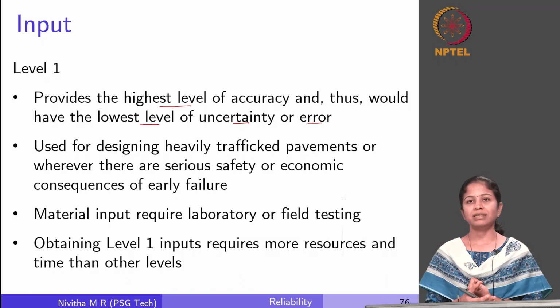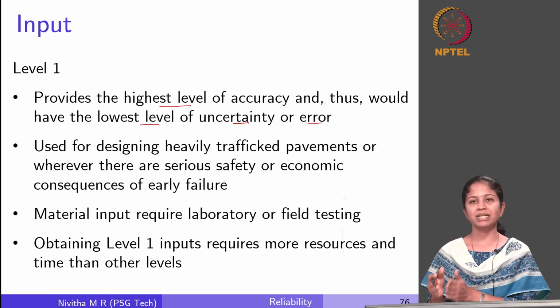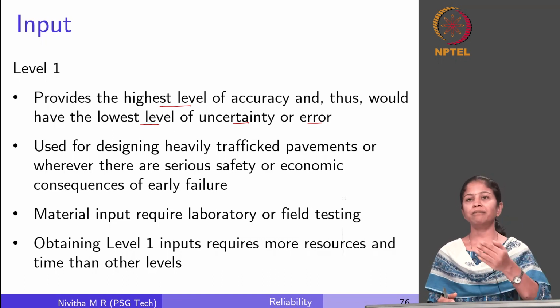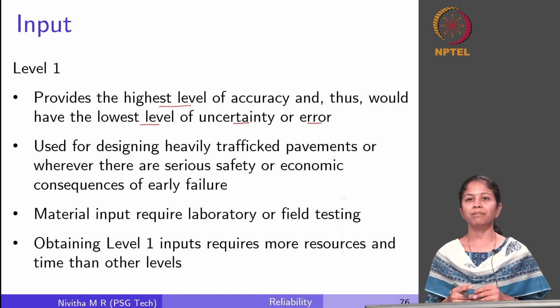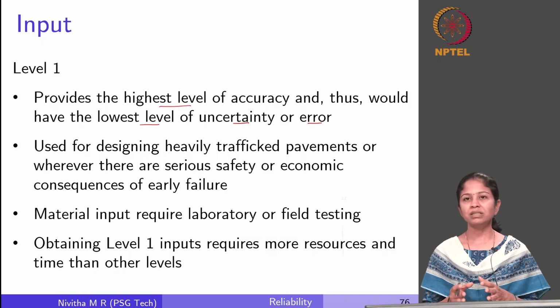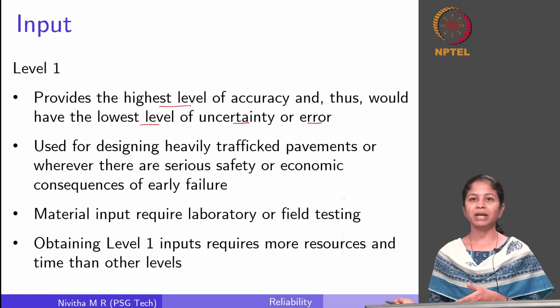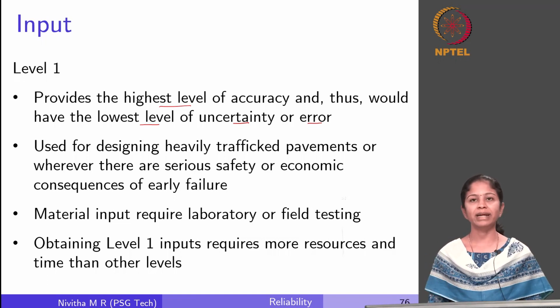Again, you know that this test has to be conducted at different frequencies and different test temperatures. So I conduct the test at all those frequencies and test temperatures. I input this information into the design procedure, and the design procedure will arrive at a master curve for this, so that for any combination of temperature and frequency the modulus value can be arrived. So this is a more close representation of the modulus that the material will be experiencing in field. Right, so this is called as a level 1 data.